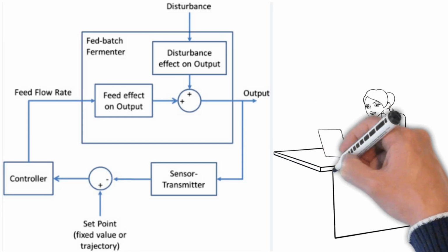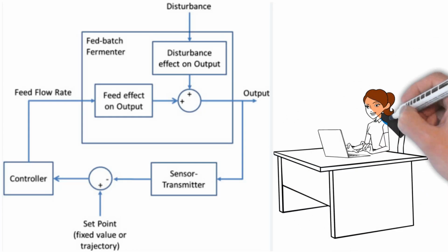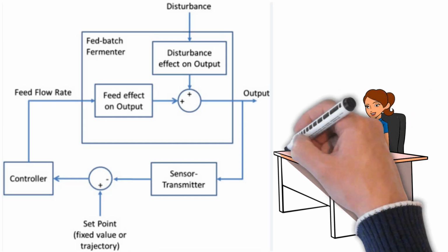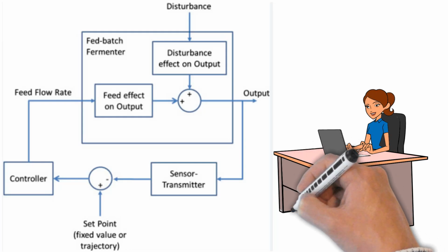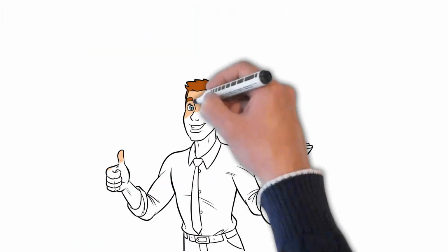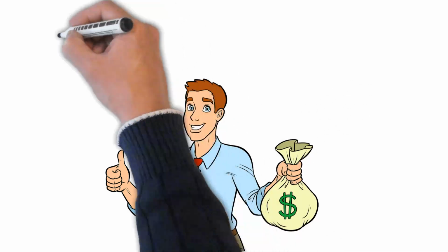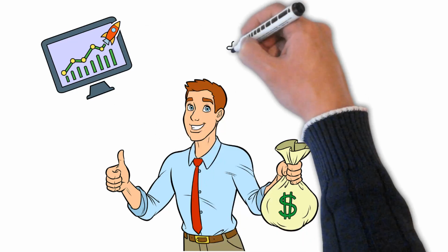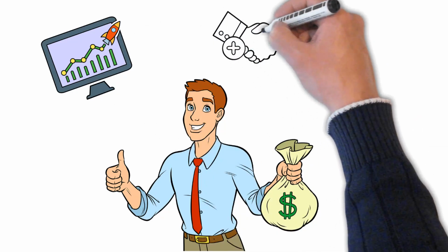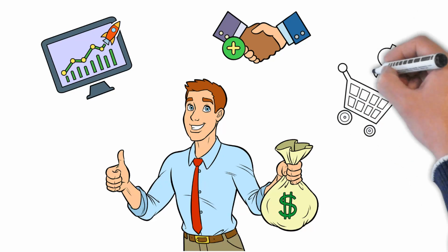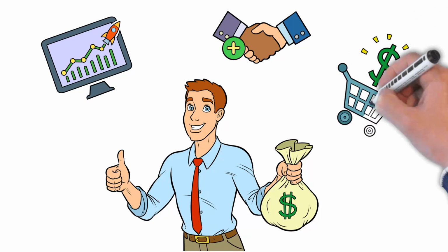This could involve using sensors to measure the oxygen concentration in the exhaust gases and adjusting the compressor's operation to ensure the fuel cell operates within its most efficient range. In summary, selecting the right air compressor for a PEMFC system involves choosing a compressor type that meets the system's specific requirements, implementing effective control strategies to ensure the air supply is precisely regulated, and adhering to safety considerations to mitigate risks associated with hydrogen fuel cells.